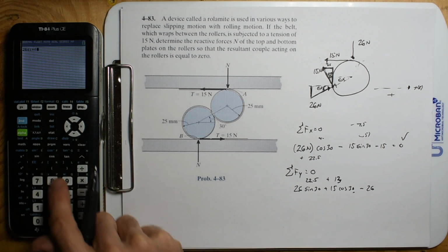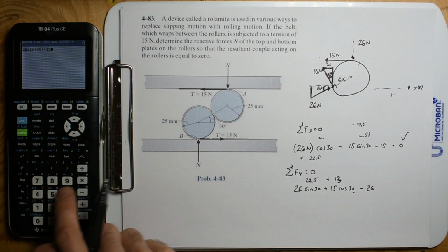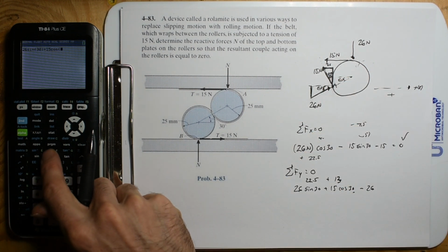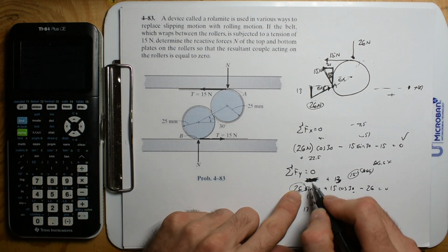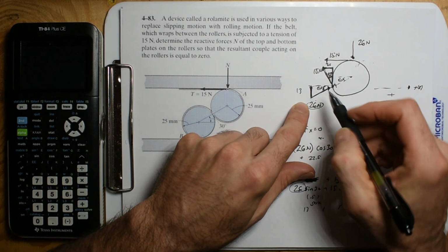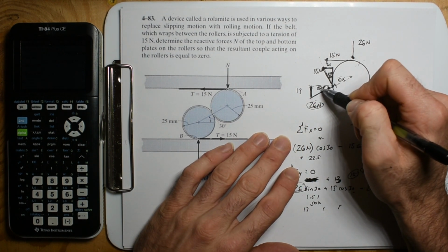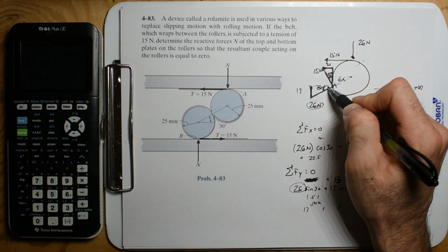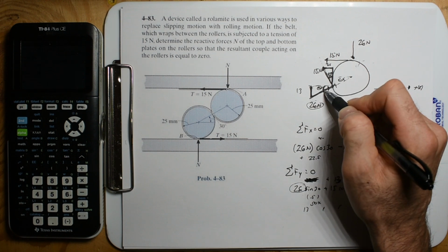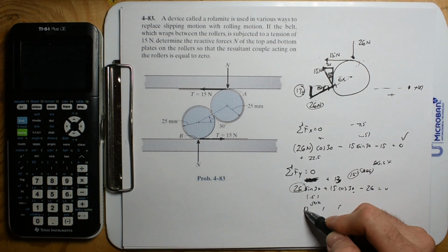So 26 sine 30. Yep, I'm satisfied with that. Plus 15 cosine 30. All right, sorry about that. My camera ran out of juice. So, yeah, I did make a hiccup. I said this was going to be 22.5. No, this is a shallow angle. It's 30. We want the vertical component. This is 30, so we want the sine component. So the sine component of this is 0.5. So you can see that if this hypotenuse is 26, this component's only going to be half of that. So we have 13 newtons there. So in the vertical direction, this is going to be 13.